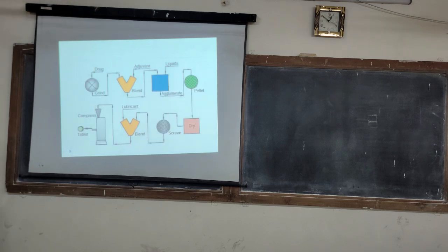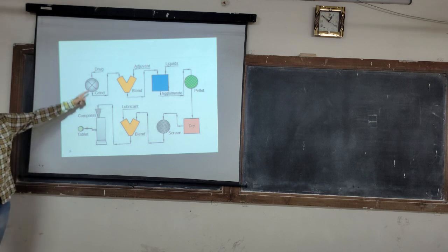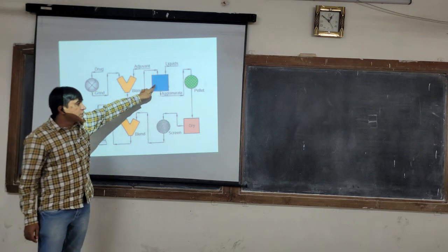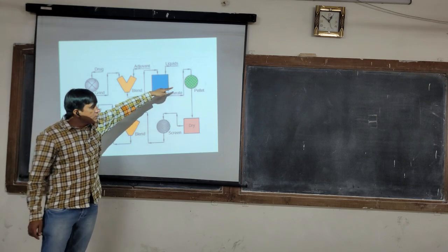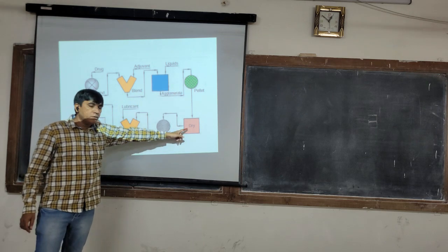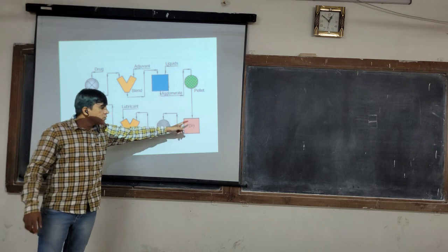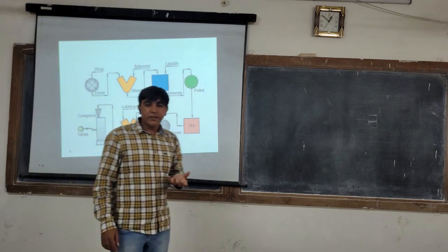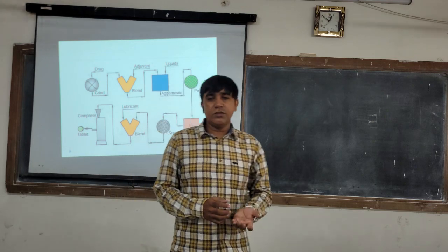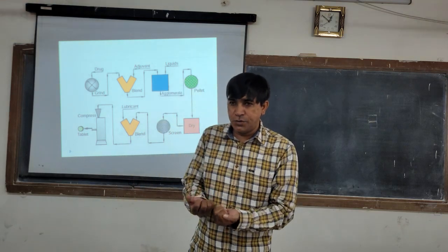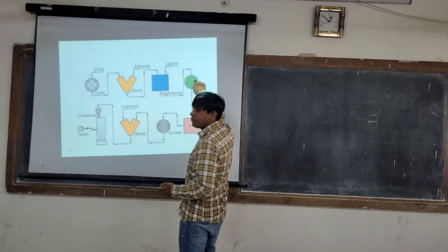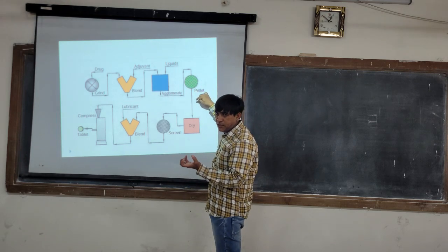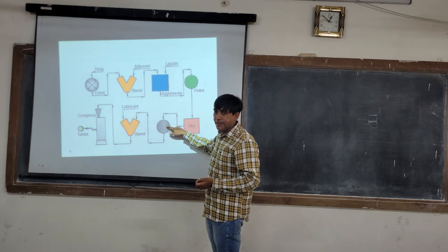This is a flow sheet of tablet manufacturing. The drug is ground and blended, liquids are added to prepare agglomerates, then it is passed through a screen to prepare the granules, then they are dried and screened again. During drying, there are sometimes chances of shrinkage of the granules. When we pass through the sieve, the size is larger. After evaporating the solvent, size decreases to some extent, and that's why we go for screening again.